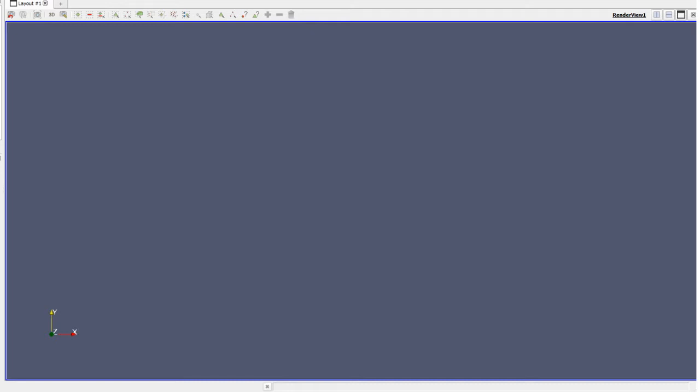My plan is to go through all the cars, all 10 teams' cars, and have a look at them. Try and do one or two a day. I'm just using a simpleFoam analysis of them, with RANS, as it's quicker than the LES one. And then I'll just quickly load into ParaView and go.